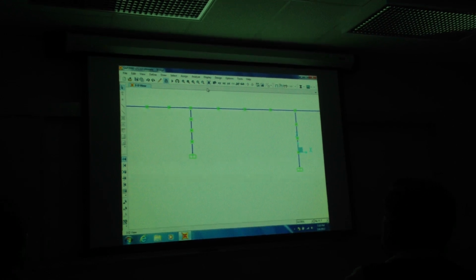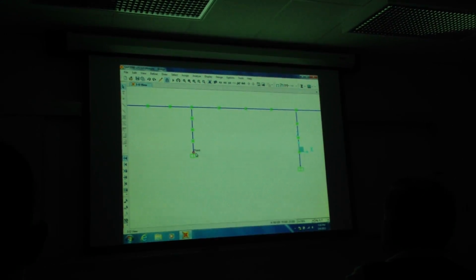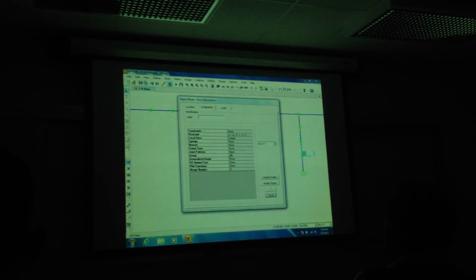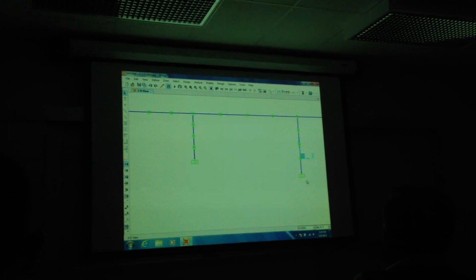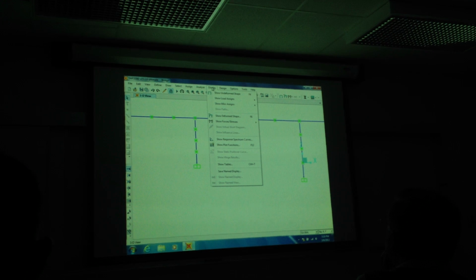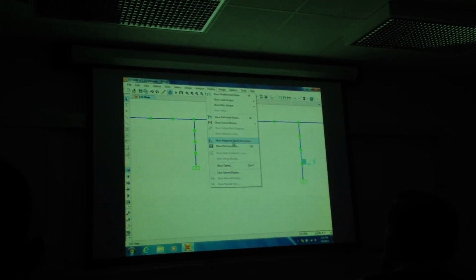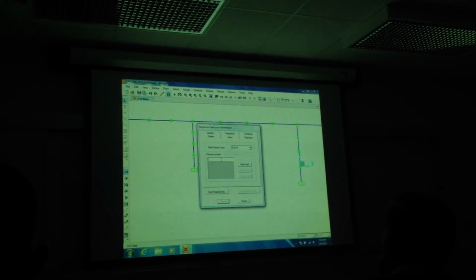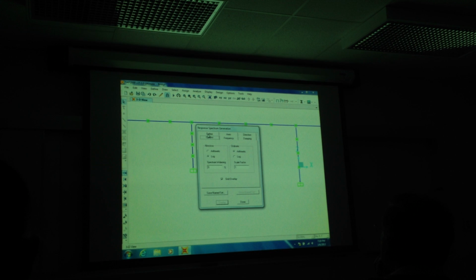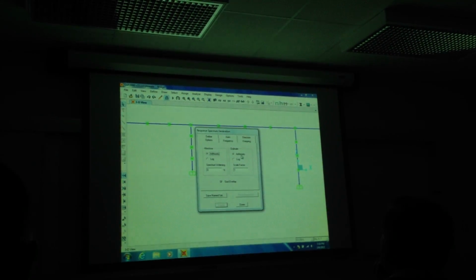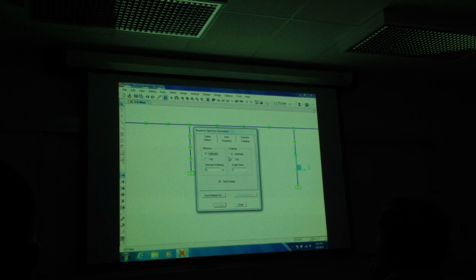So let's go back down to this joint. You have to pick a joint that's at a fixed location, because that's where the earthquake's coming in. Right click on it, and it's joint number 3. You can use any of these and you get the same results. Then click Display, Show Response Spectrum Curve. See? It's right there. And you say joint 3. Over here on options, I don't want it to be a logarithmic curve. I want it to be arithmetic versus arithmetic, so rather than log, it's much cleaner.